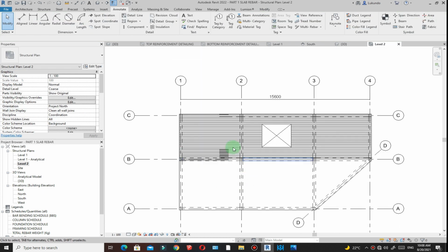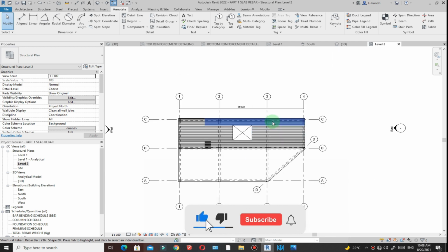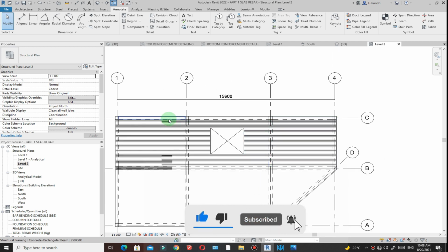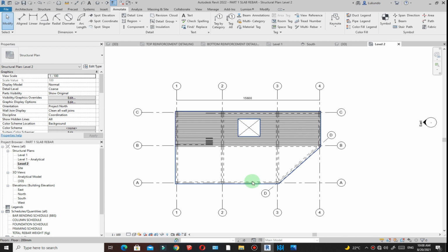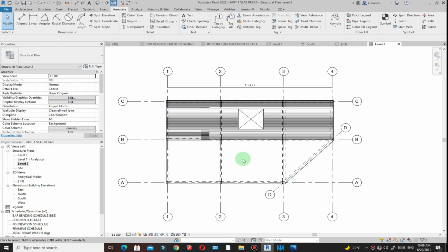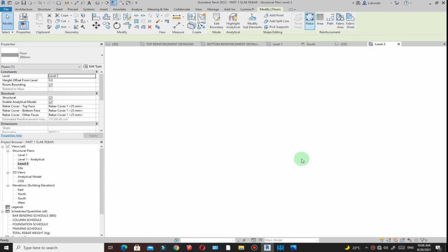All right. So I'm happy with what I have. So you can go ahead. If you check here, you see that I have different rebar sets from here, as you can see. So now for this part, I also need to make sure that from that end to there, it ends up somewhere here because it's more than 15. But for the sake of this tutorial, I'm just going to place the rebar all the way up to the end. So I can still go back to there and click on rebar.